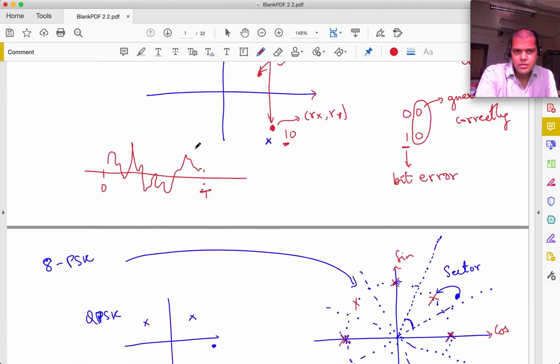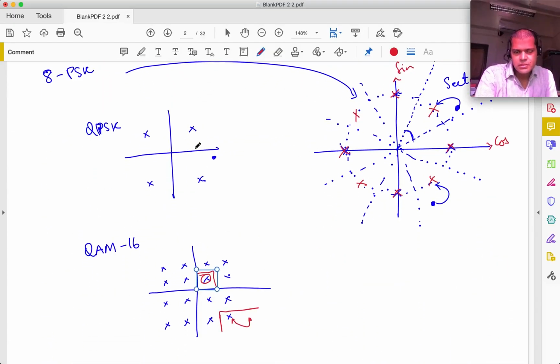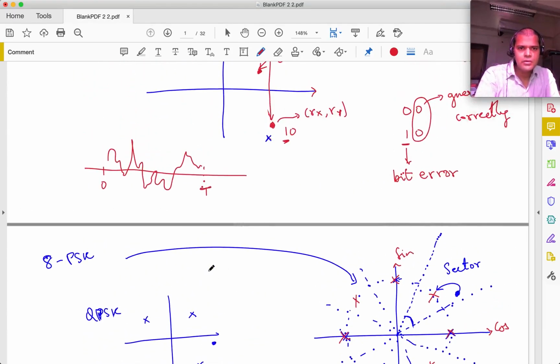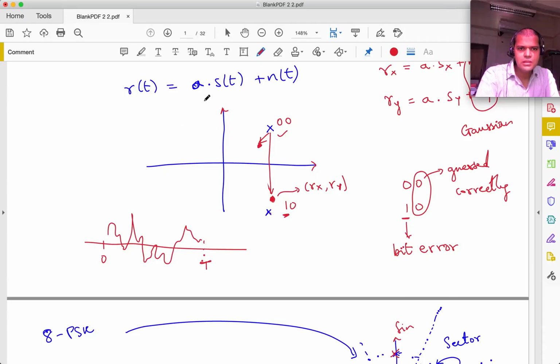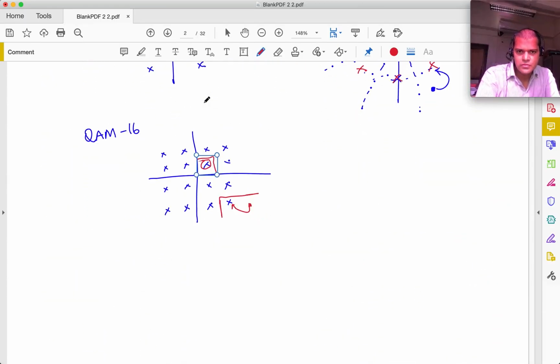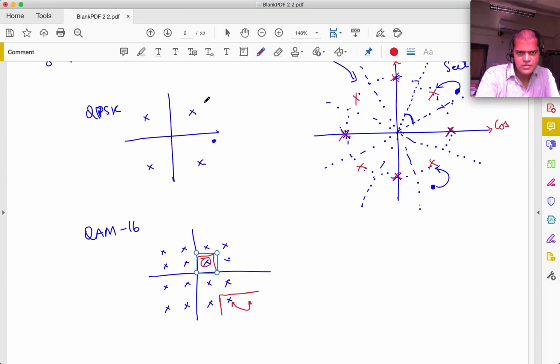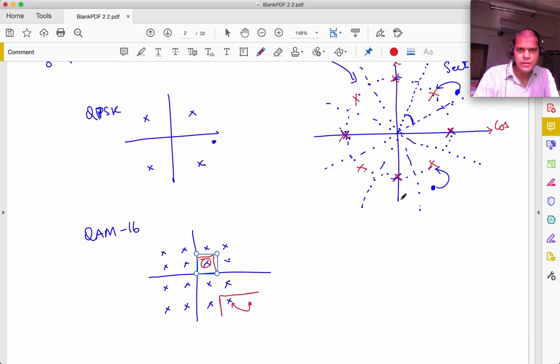Okay, so just because here this is transmitted, but what you receive is these set of constellation points which are sort of squeezed together. Okay, so here you would have to know the exact attenuation very well, otherwise you could easily guess the wrong constellation point which was transmitted. Okay, whereas here it may not be as bad.